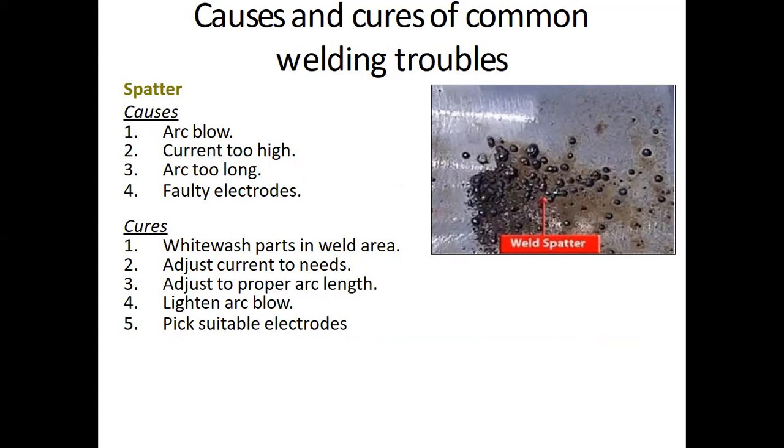So that is what is called spatter, right? Or you can even call it scatter, S-C-A-T-T-E-R. That is another way to define it, that it is distributed. The weld metal has become so fluid, completely melted, right? It is liquid now. So it has no control and it is flowing here and there. That is what spatter is. You can see here that weld metal has been thrown everywhere.